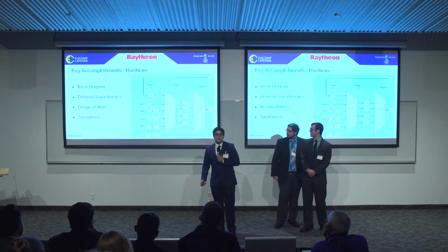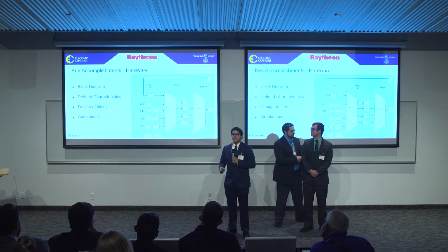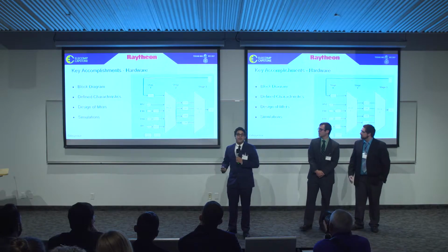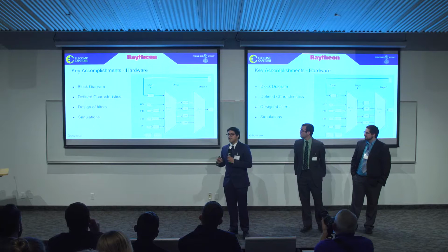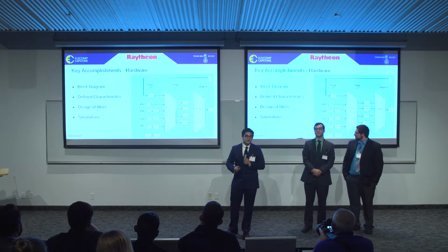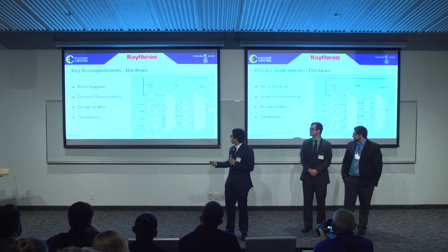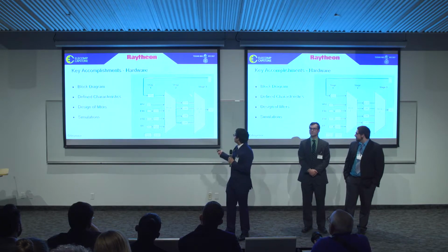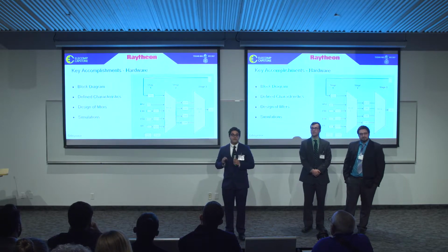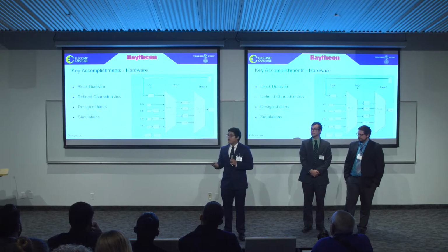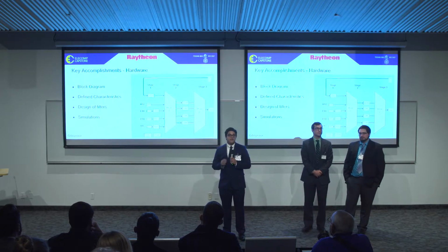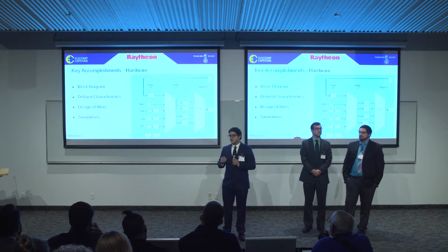For the hardware section of the project, I started designing the block diagram and defining the functional characteristics, such as the total gain needed and the gain needed per stage. After I finalized defining the functional characteristics, I was able to start designing the filters. I started by designing the low-pass filters in stage 2. In stage 2, we'll also offer an amplifier circuit with no filter. When I was done designing the amplifier circuit, I moved back into stage 1 and designed 4 bandpass filters for each individual hydrophone. These are active bandpass filters, which means they add additional gain into the signal. The reason that we want to add additional gain into the signal is to maximize the input range of the ADC, which connects to the FPGA.